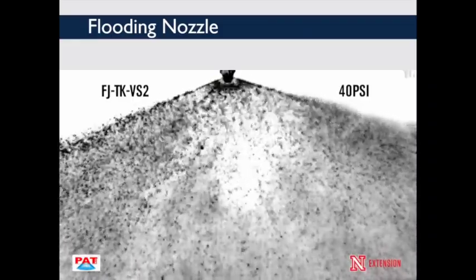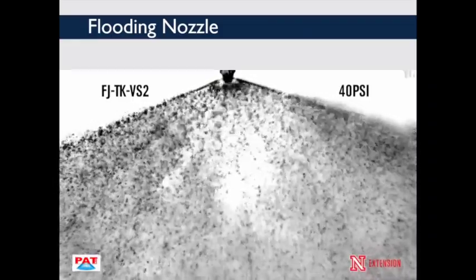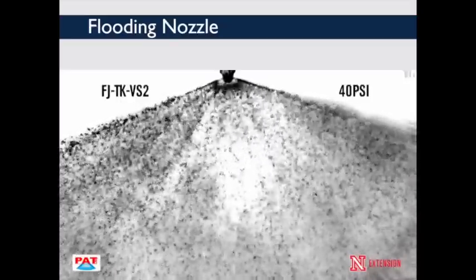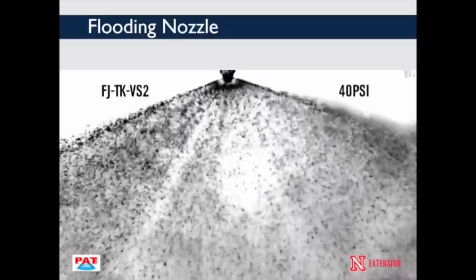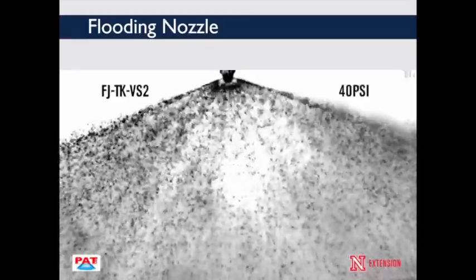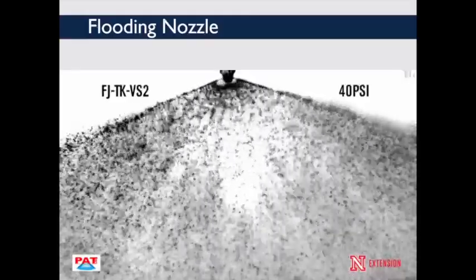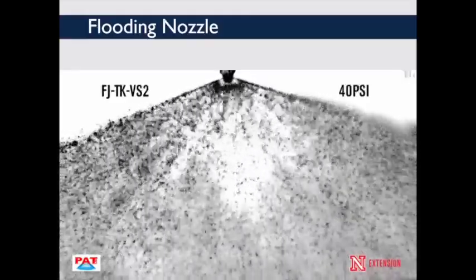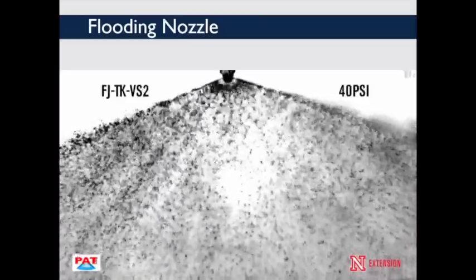Here is a flooding nozzle in action. Notice the heavier band of spray at the edges of the fan. Also note the wide range of droplet sizes produced. The gray clouds are small droplets. Because flooding nozzles are so pressure sensitive, special care must be taken to maintain operating pressure.